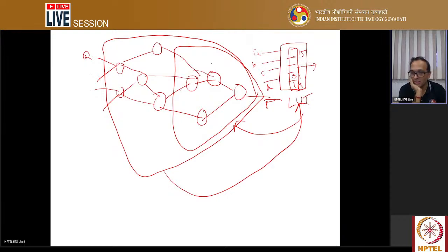What I'm trying to mean here is that this area optimization that you talked about is finally how many units of resource you're using. So this is a very well-known metric: how many LUTs are you using, how many DSPs are you using, and so on, right? But it all depends on how your tool is implemented. So in this design, if somebody gives me one LUT, that is the best possible mapping. Probably if you take this one, then you have to take many other cases, right? Because now this can be one more mapping, and then this can be one more mapping. So there are 3 LUTs you might need here.